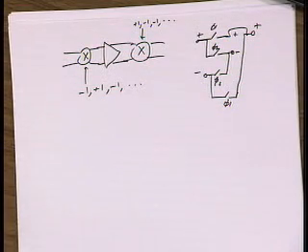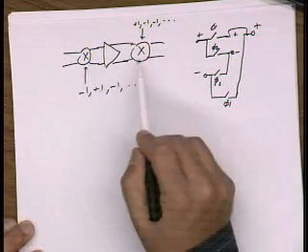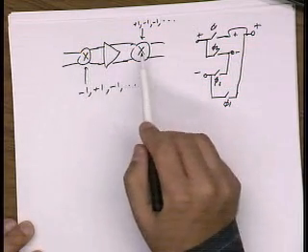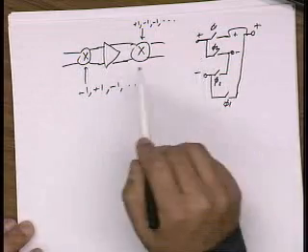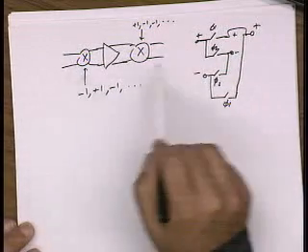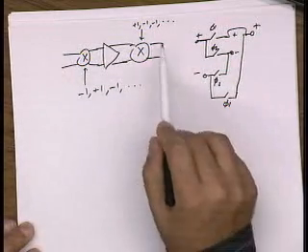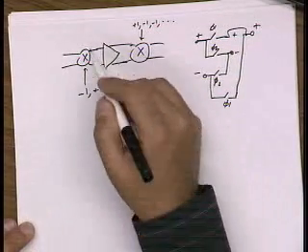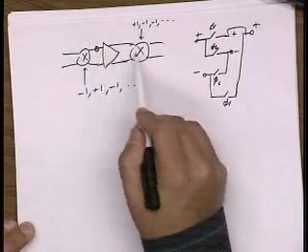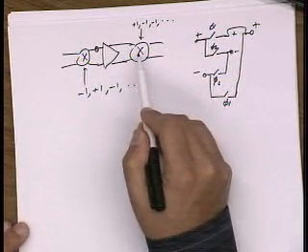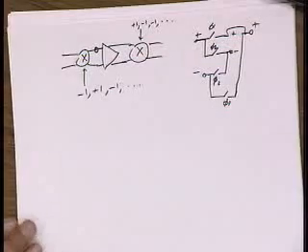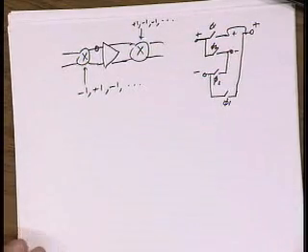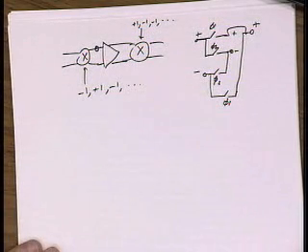You might say, well, what happens to the DC voltage? Well, because the transfer function here, if you think about it, if I multiply by plus 1, I get the same thing. Minus 1, I get the same thing, right? So the net transfer function for the signal is that it doesn't see this at all. Whereas the transfer function for the offset voltage, which is here, is that it gets modulated only once. And so it actually moves out of the band. So what you're doing is you're modulating the offset voltage out of the DC band where you care about effectively, and it goes away.